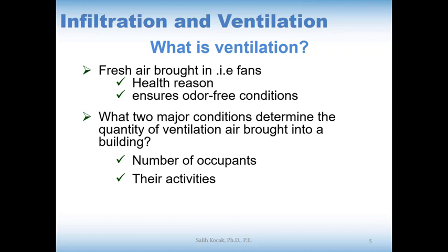And if we have 10 people inside this place, we need at least 150 CFM. And their activities are important also. So if it's a theater with 500 people inside it, or if it's a gym with 500 people inside it, the requirement is not going to be the same.